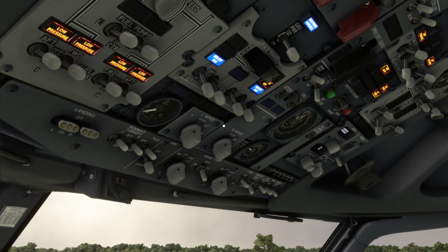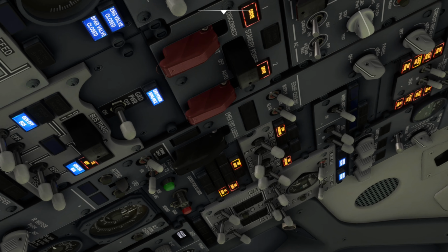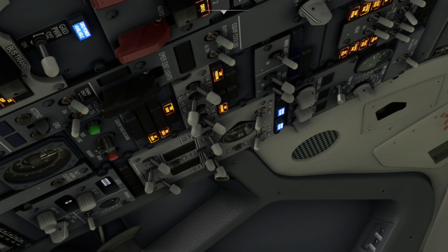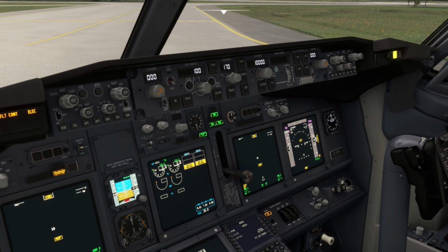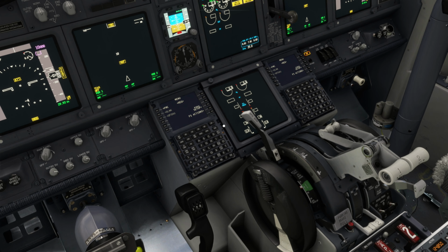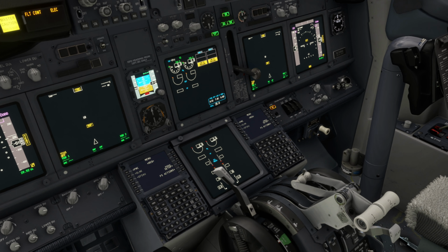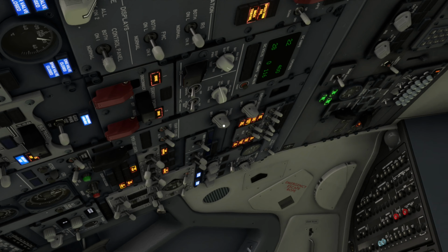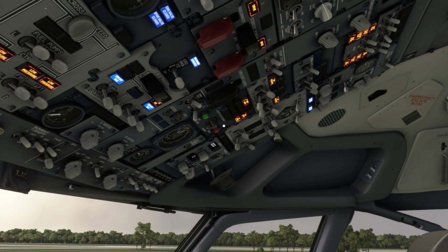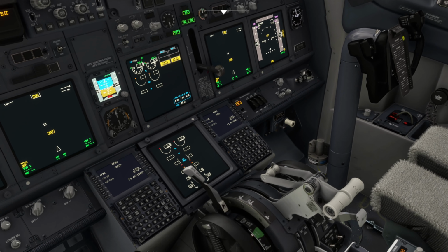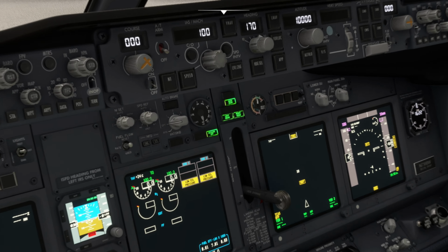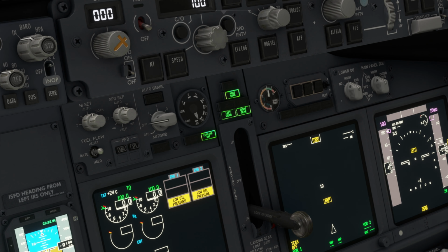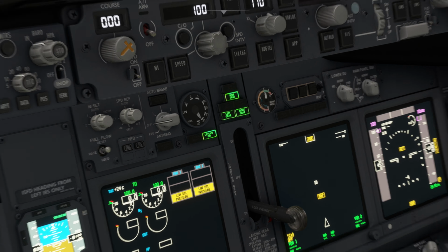However, here with the APU running and our electric hydraulic pumps actuated here on the hydraulic bus, we can say that we have got hydraulic pressure sufficient to actuate the flaps, slats, and spoilers as we have just demonstrated. Let's shut the spoilers now, back into the flight detent, which means no spoilers are deployed. And in addition to that, we have our flaps at 40 degrees. We can also retract the flaps if we want, bring them back to the completely retracted detent at 0 degrees. And you'll see that here on our indicator as it starts to scroll back up from 40 to the up position.